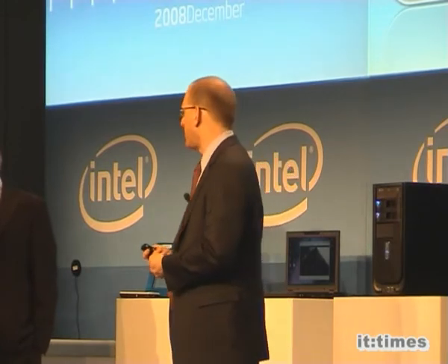And similarly, if we took the same point in the curve and kept the performance the same, to see how much current we could save, you see the leakage current goes down by a factor of 5 for the N device, and a factor of 10 for the P device. So we have succeeded, based on 2 years of high volume manufacturing experience with high-K metal gate technology at 45 nanometer. We've been able to use that experience to deliver a next generation version of high-K metal gate that delivers superior performance.